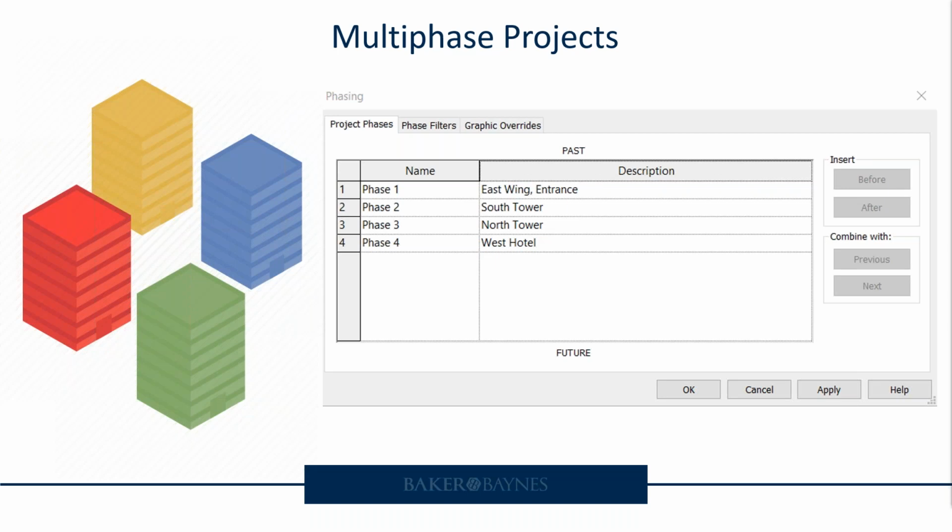more easy to recognize. And then very important when you are working with multi-phases is to pay attention to the sequence in which you are adding them. So in other words, your first phase needs to be closest to past at the top, and then your latest or current phase needs to be closer to future at the bottom. The reason I'm saying this is because once you've added phases, you can't rearrange or delete them. So be careful when you do the setup that you add them correctly.